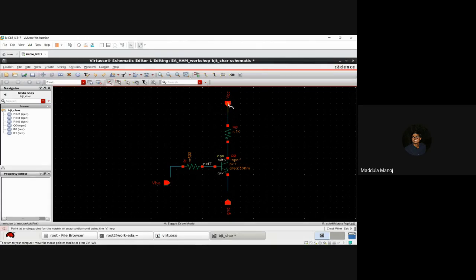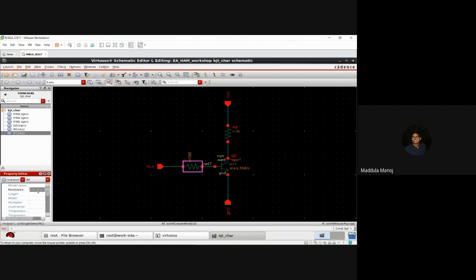Once you have created these pins and connected, save the circuit. Once the circuit is saved, if it doesn't give any errors, you can change the resistor values first. Let's keep a resistance of 500 ohms, or you can type 0.5k in the resistance. And at the output, a small resistance will suffice. A resistance of 100 ohm is enough.